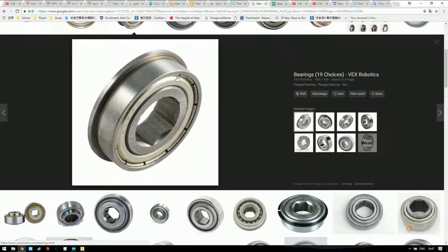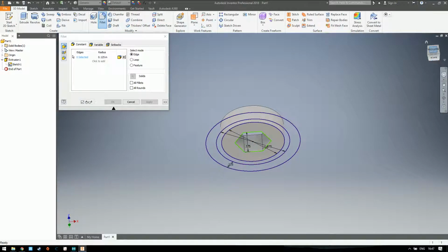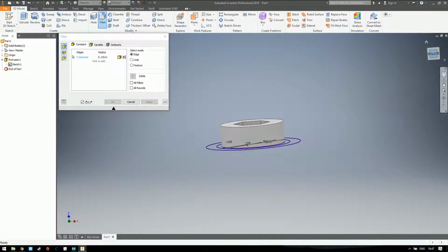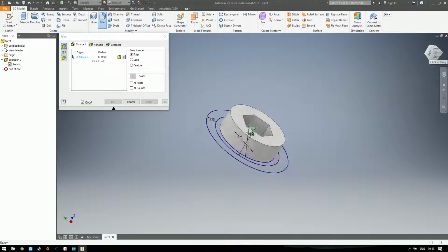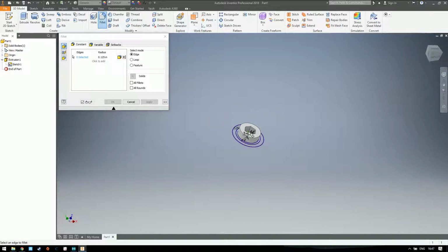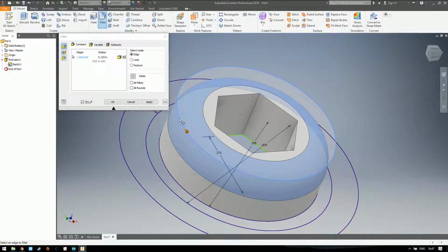Yeah, just over here. So what I'm going to do is make that curvature appearance. Oh yeah, by the way, you can also left click on the cube and just drag it. It will show you the pivot. Also use the wheel on the mouse to adjust the size of your graph. So you click Fillet, then you click on the side where you want it to start a little bit of curvature. See?